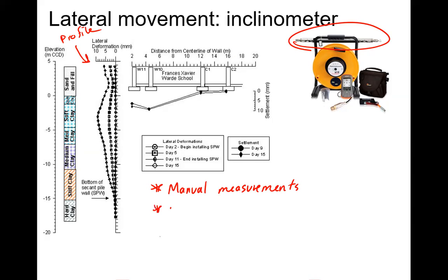The other important thing with this is our datum is equal to our ground surface. So this is our 0 mark. So where we put this ground surface is important. And I'll show some pictures here in a second. Think about it like if some of these projects are for settlement, that means our ground surface is going to change. And hopefully our ground surface, our datum, is settling. So we need to consider that when we're actually installing these inclinometer tubes, because our datum could potentially change.